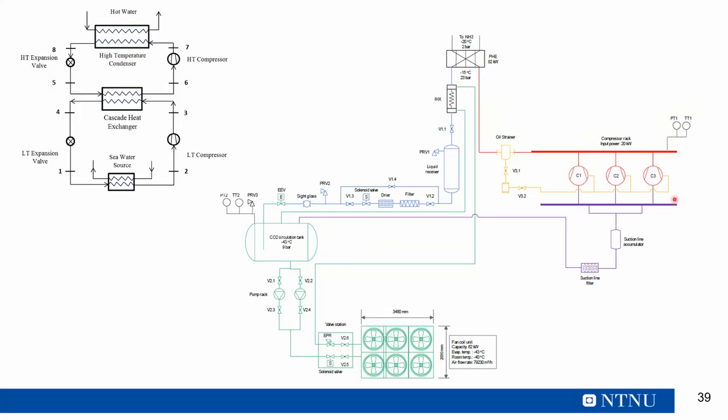In the same way, we are proposing a number of different compressors, in a pivoting kind of arrangement. The compressors will work according to the load requirement and the capacity of the unit, so they will stay in parallel. The system will have a common heat exchanger known as the cascade heat exchanger.